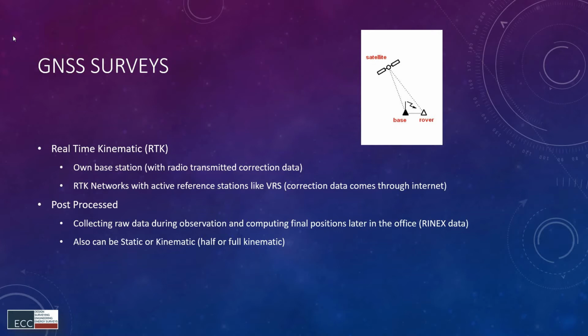And we download those RINEX data files, and we just calculate that point first. So after we calculated our base, it will be a known point.